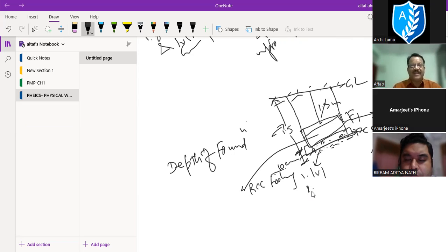And number two criterion is, as per the soil testing report or as per your experience as a good architect or civil engineer, you are expecting that at this level you have attained the required SBC, soil bearing capacity, maybe 150 kilonewton per square meter or 200 kilonewton per square meter, for which this foundation footing is designed.